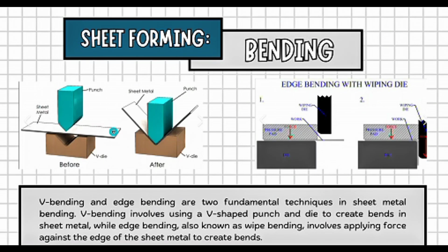So in V-bending, the sheet metal is bent between a V-shaped punch and V-shaped die. So included angles ranging from very obtuse to very acute can be made with V-dies. It is often performed on a press brake, and the associated V-dies are relatively simple and inexpensive.